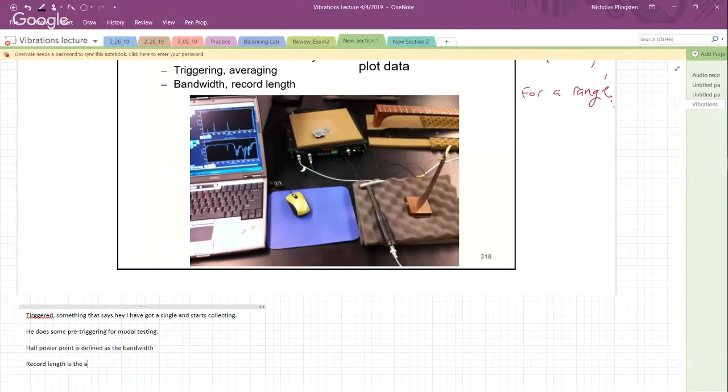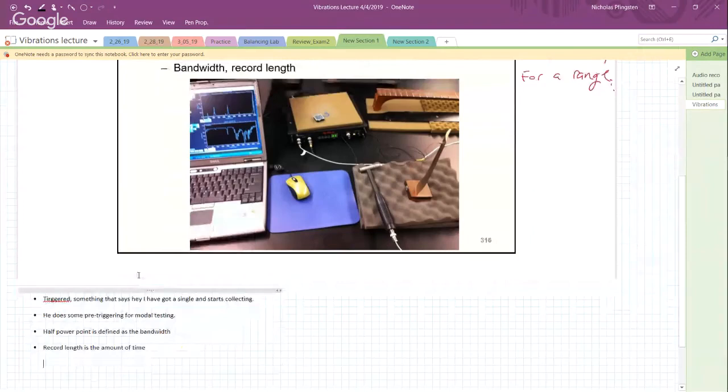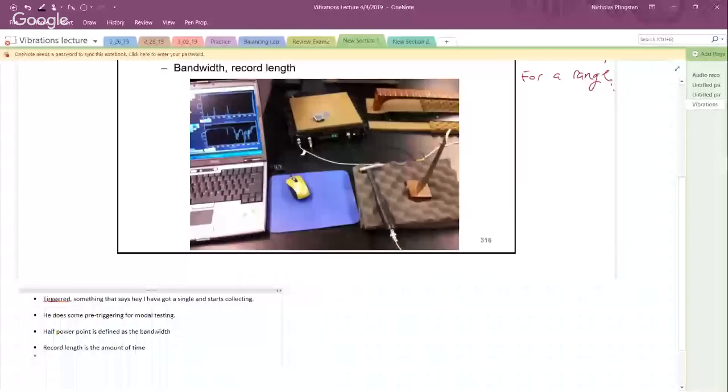And I'm going to show you some different traces. There's some different data. We'll look at the time domain data. We call that time traces or time records. We'll look at the auto spectra. We talked about them just briefly. I told you not to worry too much about that page, but we'll talk about the auto spectra and power spectra. Those two quantities are used to calculate the frequency response. I like to look at those to make sure that the data doesn't have any problems.